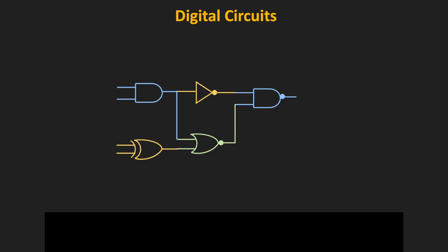And any logic operation which can be implemented using these logic gates can be expressed using a Boolean expression. And using Boolean algebra, it is possible to minimize the Boolean expression. So this minimization of the Boolean expression is also a very important part in digital circuits. Because with the minimization of the Boolean expression, it is possible to reduce the number of logic gates which is required to implement a certain logic operation. So in the upcoming videos, we will learn more about these different logic gates and we will see how different functions can be implemented using these logic gates.